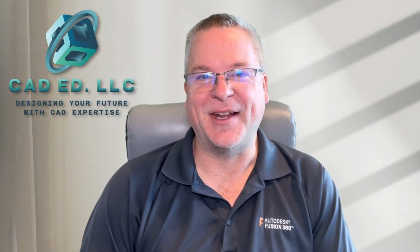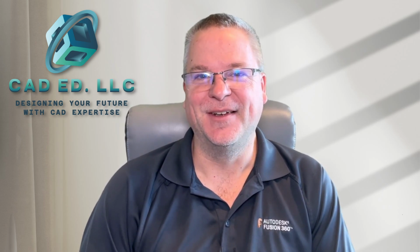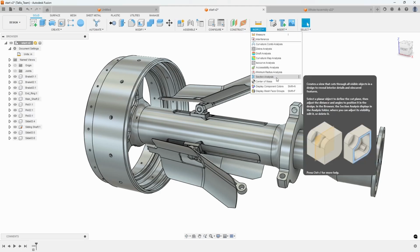In this week's video, I'm going to be talking about a command that I use quite often called section analysis. So let's take a look at how we can use this. When working with assemblies in Fusion, one of the commands that I use quite often is in the Inspect menu: section analysis. This allows you to slice through your assembly and see inside.